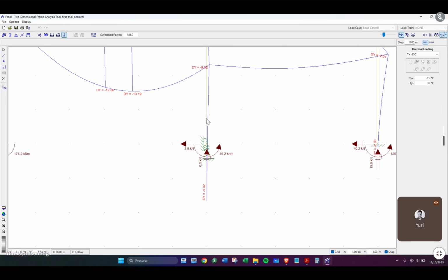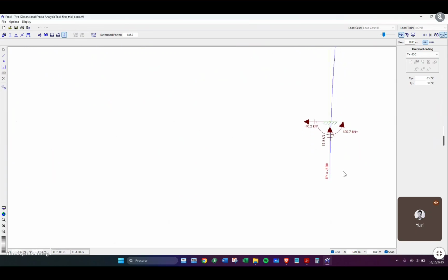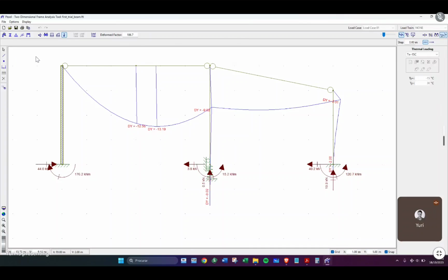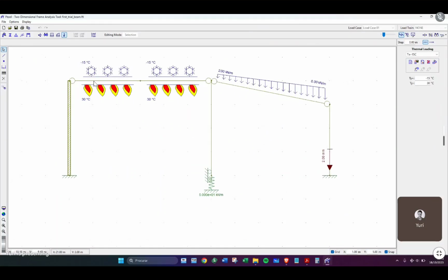So whenever we are assessing settlements of structures, if you don't define very well the spring of your support conditions to measure how much it will deform, you can have a lot of damage in your structure. Okay, and here the imposed displacement also created very stiff boundary conditions when we have that column which is very strong.